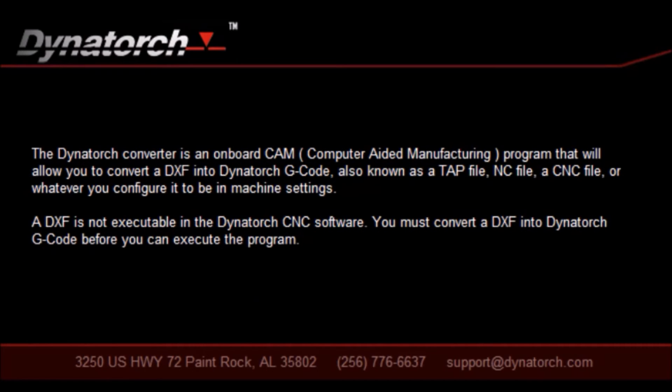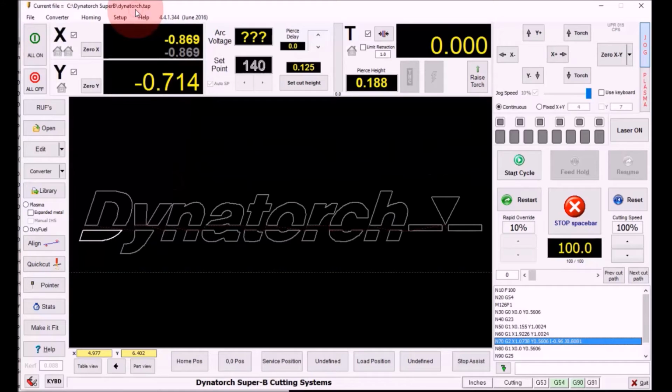The Dynatorch converter is an onboard CAM program that will allow you to convert a DXF into Dynatorch G-code, also known as a TAP file, NC file, a CNC file, or whatever you configure it to be in machine settings. A DXF is not executable in Dynatorch CNC software. You must convert a DXF into Dynatorch G-code before you can execute the program.